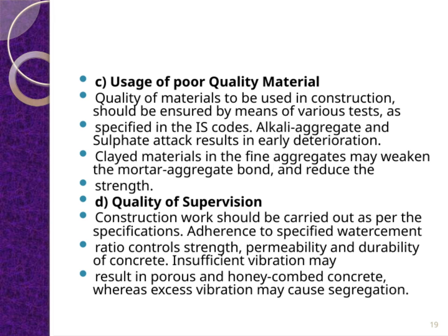Moving on to supervision, proper oversight during construction is crucial. The work must be carried out strictly according to the specifications provided. One key aspect is adhering to the correct water-cement ratio, as this directly influences the strength, permeability, and durability of the concrete. Too little vibration can leave the concrete porous and honeycombed, which compromises its integrity.